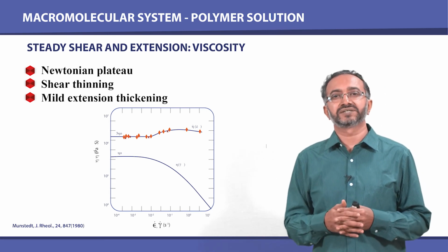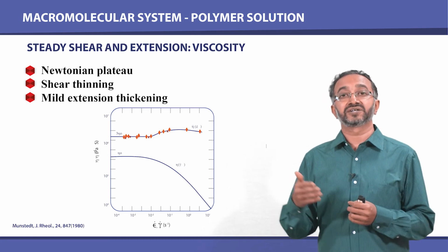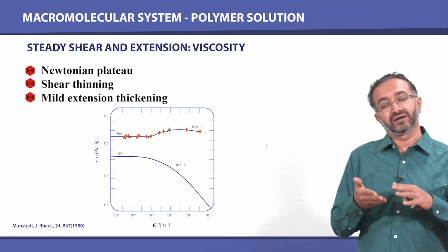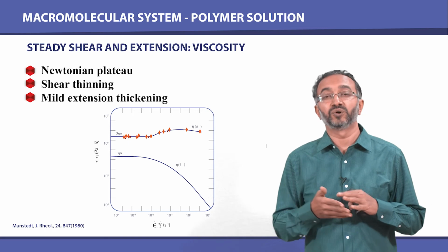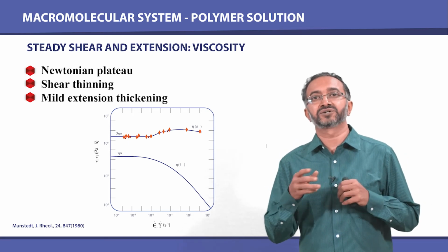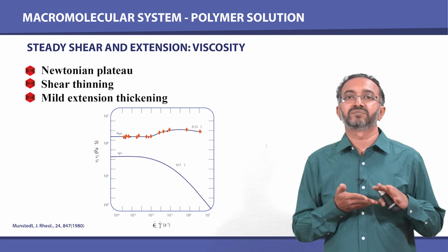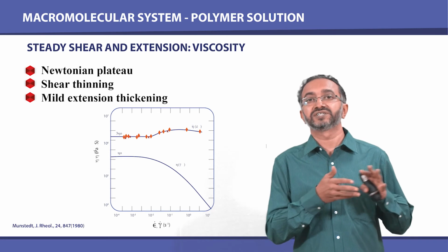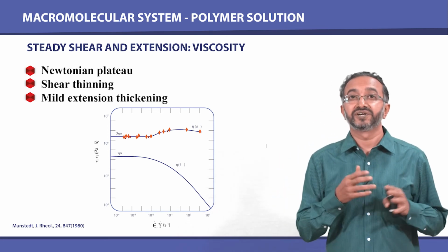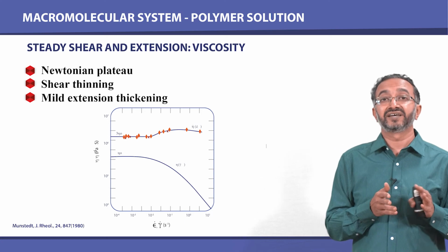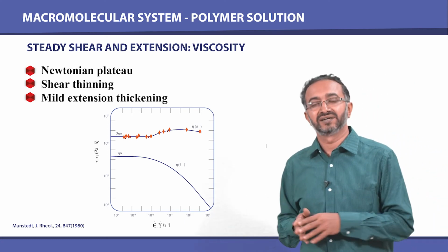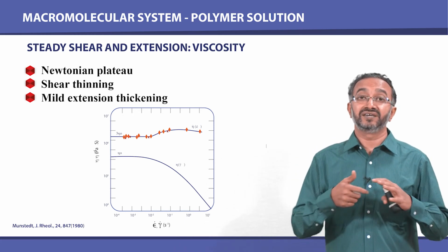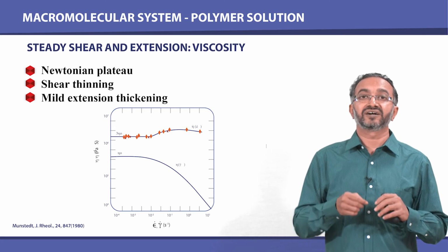Now, for a polymer melt, in case of higher and higher strain rates in shear, it appears as if the entanglements play less of a role, or in other words, because of the orientation of macromolecules, it is easier for entanglements to be slipped past. The molecule is able to move despite the entanglements being there, and therefore the viscosity appears to be less and less. On the other hand, in case of extensional response, it appears that the entanglement in fact plays a role like a cross link.